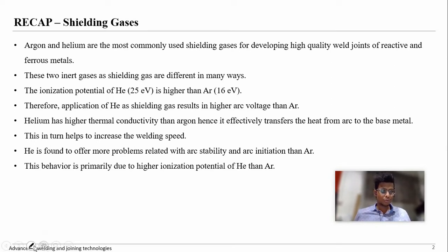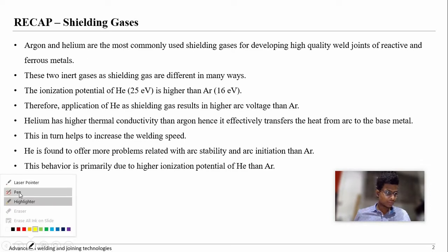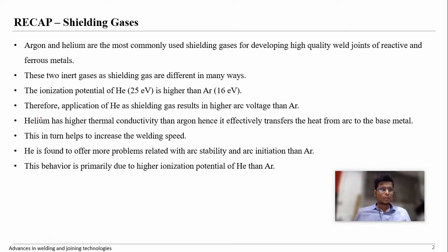So now once again I'll select it. Helium has a higher ionization potential than argon, and the thermal conductivity of helium is higher. So whenever a high welding speed is required, we can go for helium.